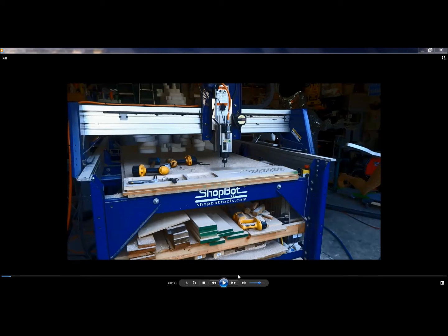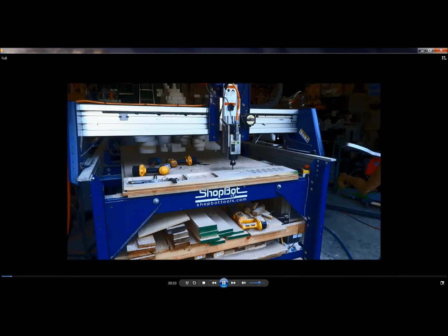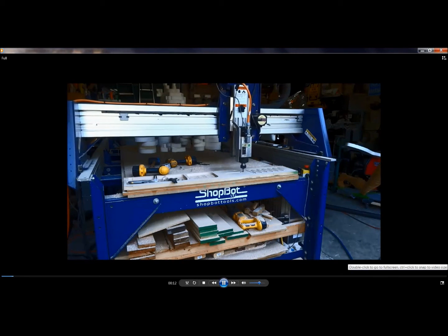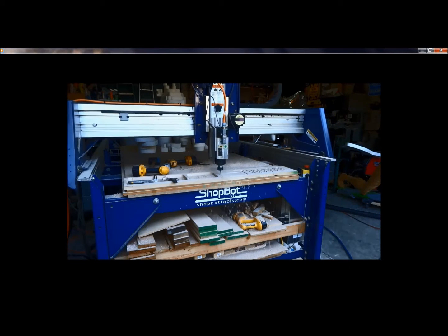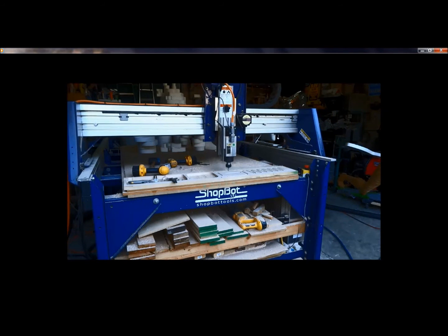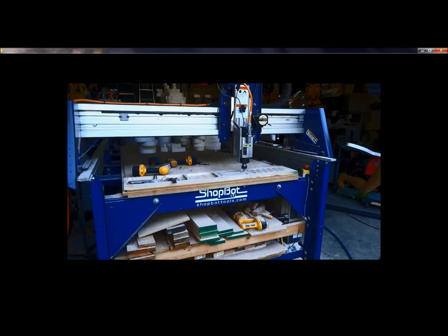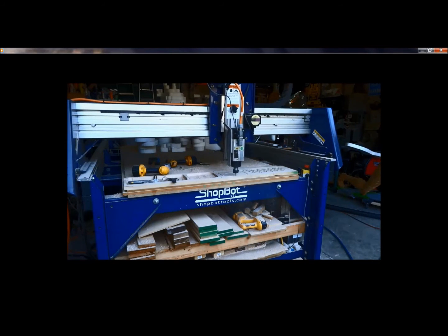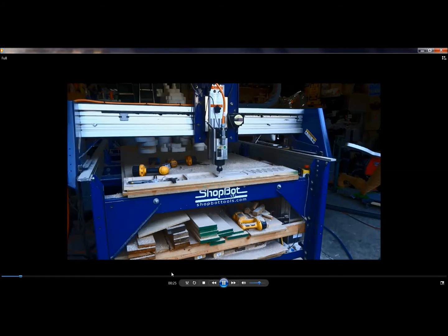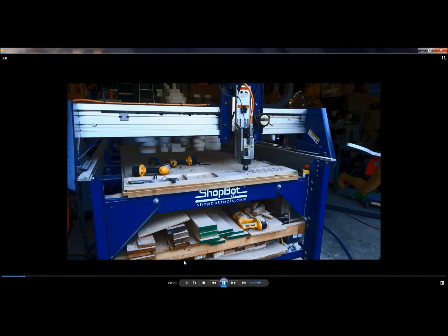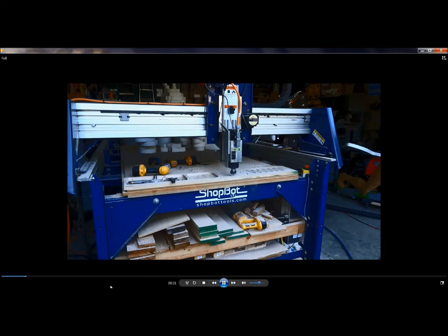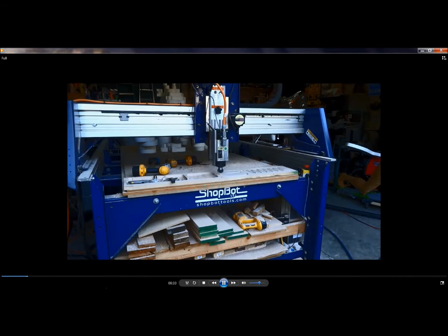Alright, we'll start here with a full screenshot, seeing the ShopBot in action. So this just to show you, this is on a 4-foot by 8-foot machine, and the way I have it is up in the front corner. So this is just a full screenshot, and then we'll dial into starting the file just like it's drawn. And again, the dust foot is only removed for demonstration purposes. You want to keep that on, keep your dust collection always sucking up the sawdust.